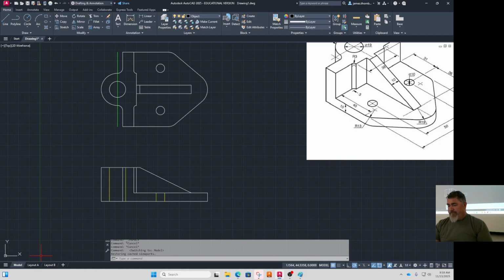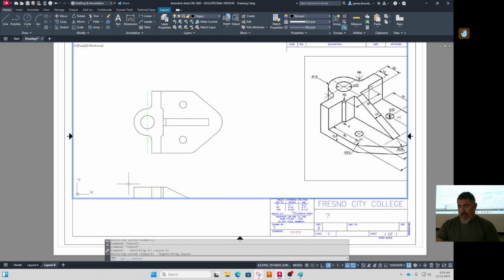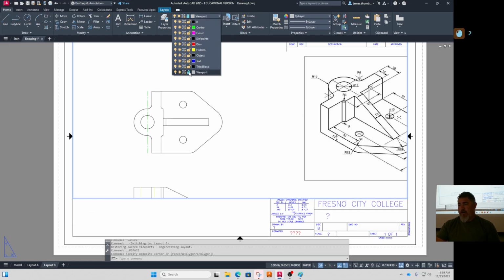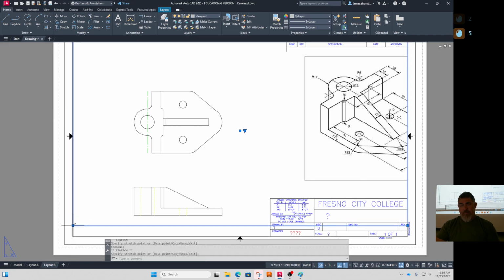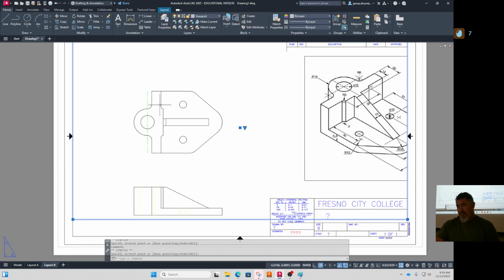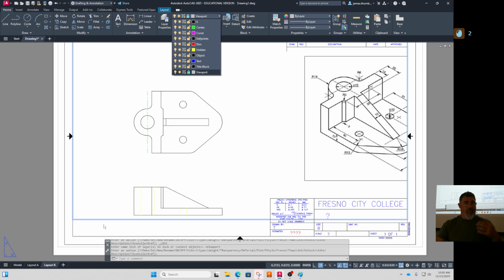All right. So I'm going to go into here. This is just my edge of my layout. So right now, my viewport layer I've got locked. So that means I can't change it. See, there's no grips. If I click on it, unlock it, now I get grips. So now I can adjust it if I wanted to, depending on how I wanted to do things. But I like to leave it locked so that I don't accidentally grab it and do stuff.